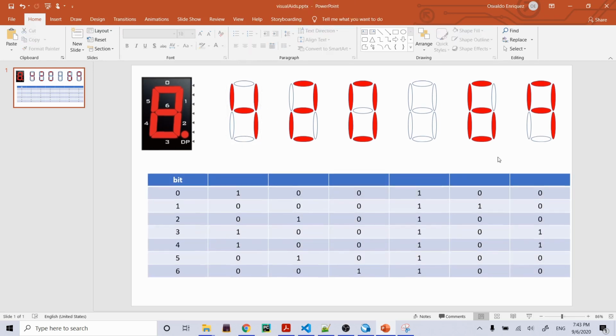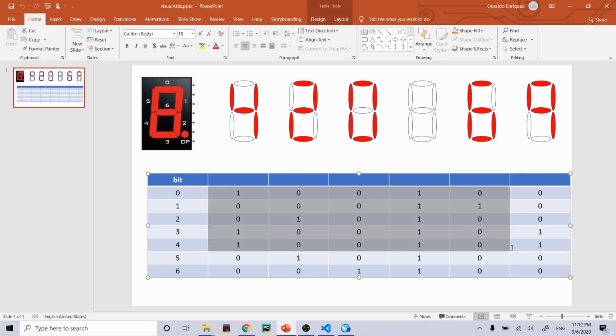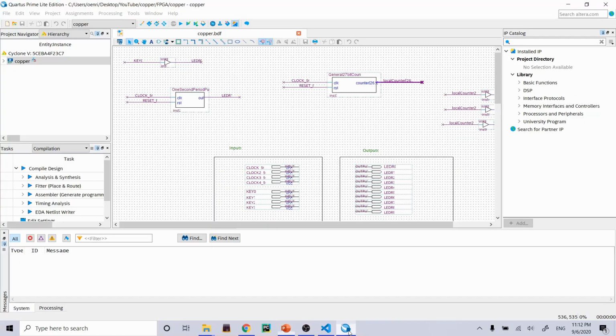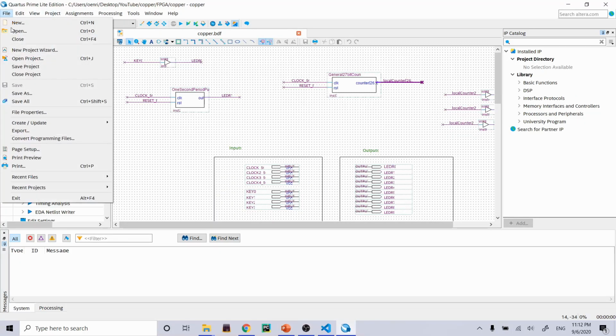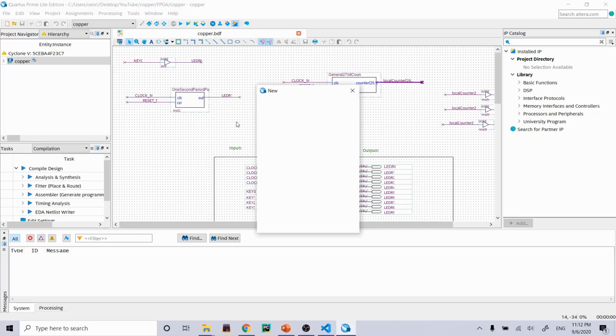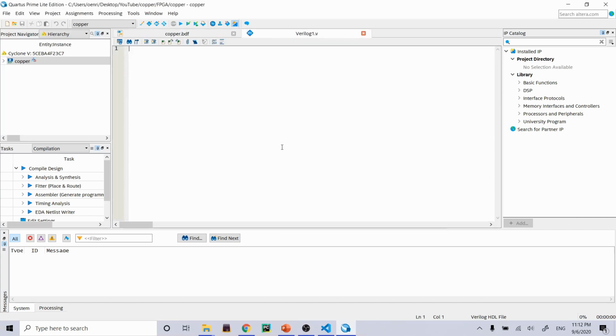Okay, so now let's actually go write some Verilog to drive this state onto the appropriate pins for all of these here. Okay, so go here to Quartus and File, New, Verilog module. Okay, so module, and let's give this one a name, and let's call it 7-segment display, just general controller. What it's going to have as an input is, you know what, I'll show you a couple ways to do this. Rev A.